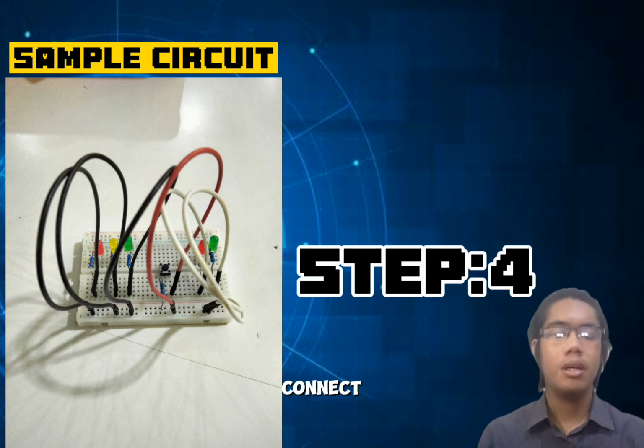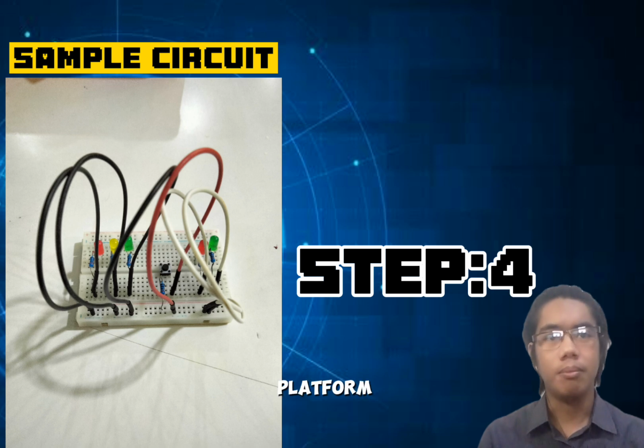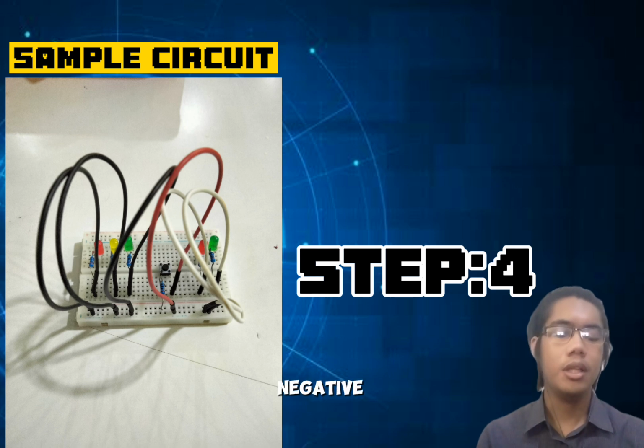Step 4. Connect jumper cables on the breadboard. In the car LED, connect a black jumper wire from J28 to the negative rail. Connect a black jumper wire from J24 to the negative rail as well. The black jumper wire from J21 to the negative rail.